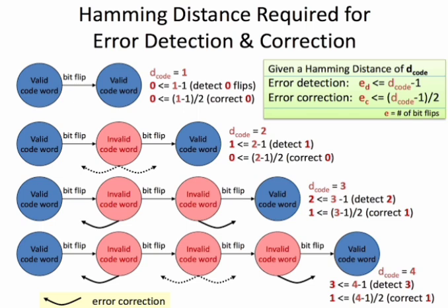Now the Hamming code for (7, 4): n equal to 7, k equal to 4, m equal to 3. m bar equal to m0, m1, m2, m3 is nothing but the message bits. b bar equal to b0, b1, b2 is called the parity bits. Then the encoded code word x bar equals m0, m1, m2, m3, b0, b1, b2. This is one way of showing the relation between b0, b1, b2 and m0, m1, m2, m3.